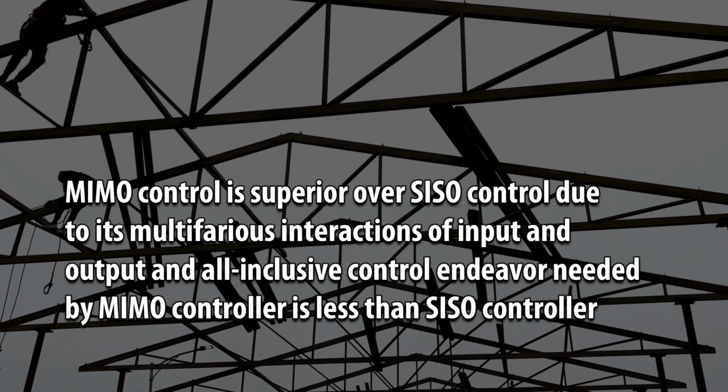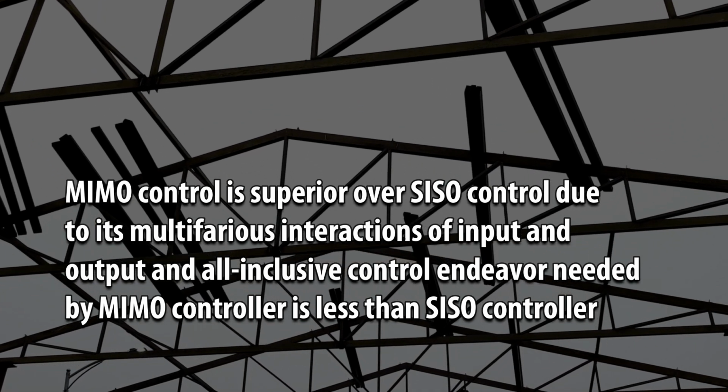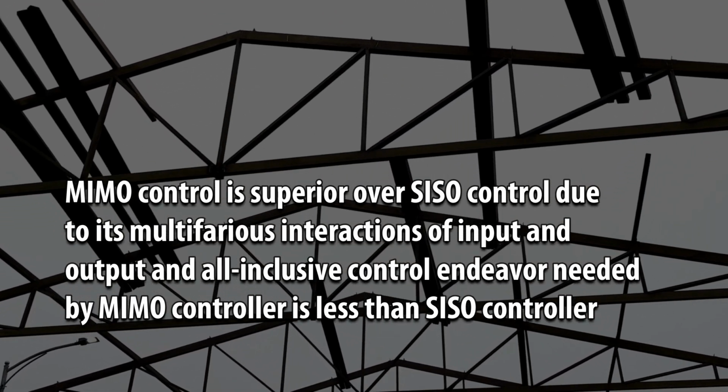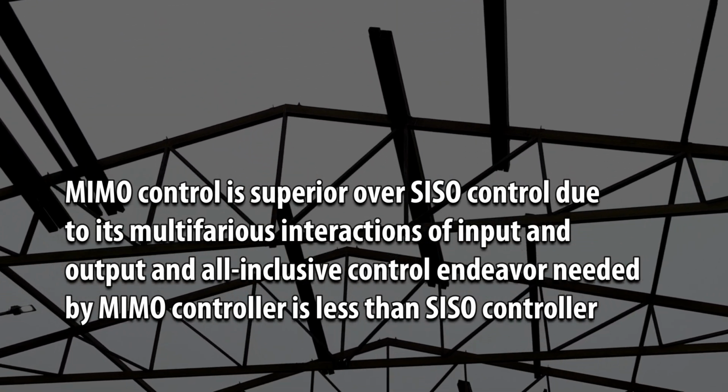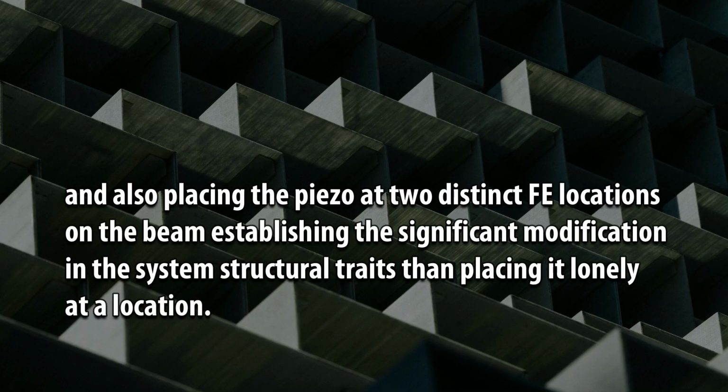MIMO control is superior to SISO control due to its multifarious interactions of input and output, and the overall control effort needed by the MIMO controller is less than the SISO controller. Also, placing the piezo at two distinct FEM locations on the beam establishes a significant modification in the system structural traits compared to placing it alone at a single location.